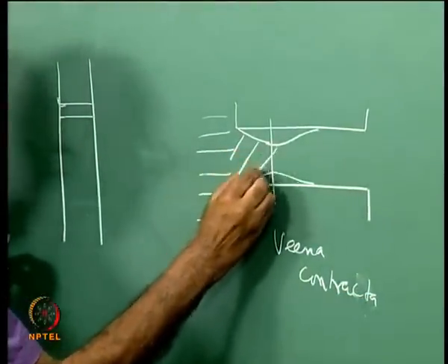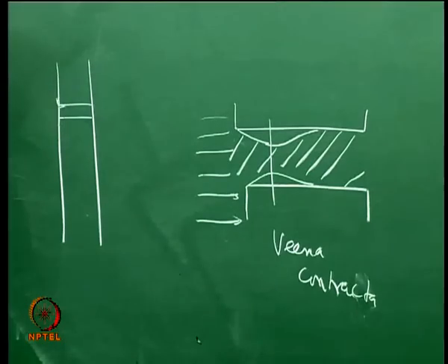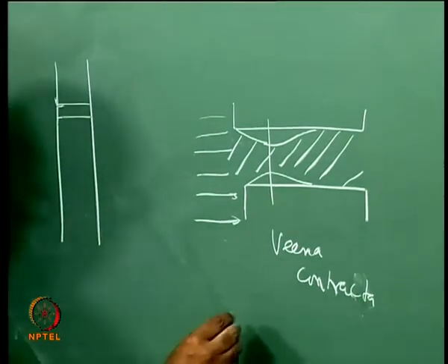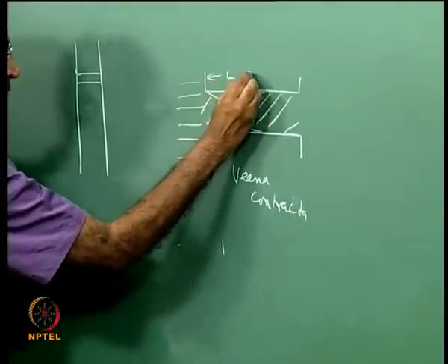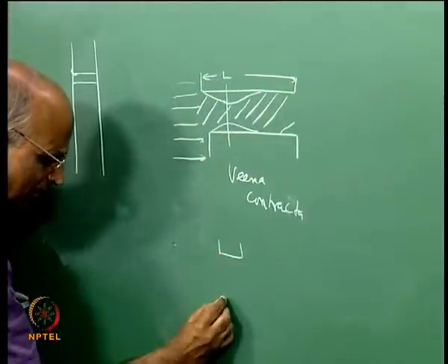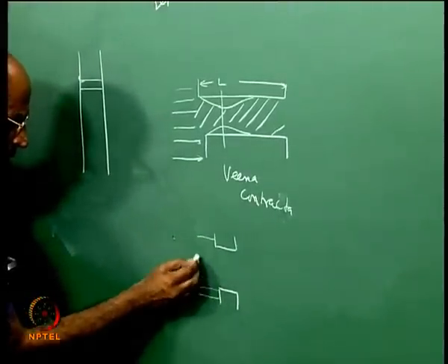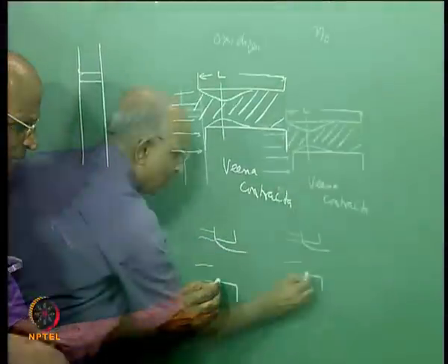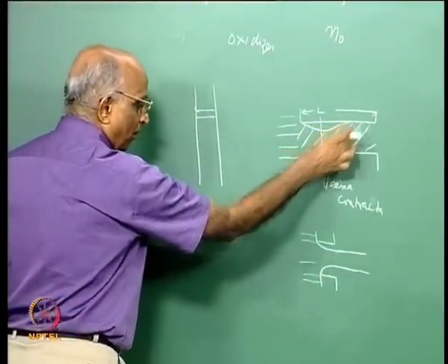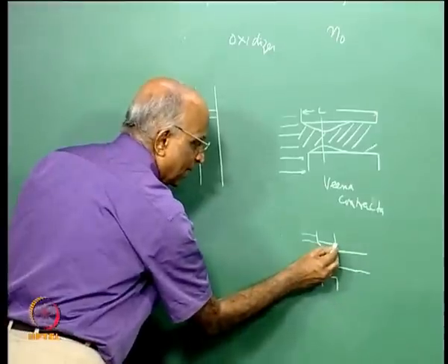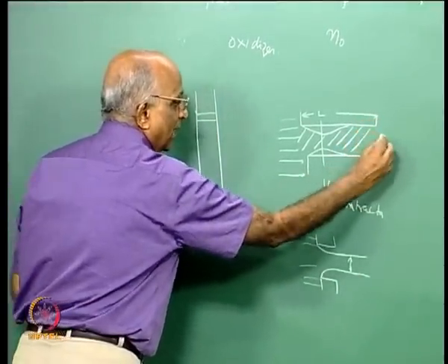In other words, this is where the liquid is flowing. If I have my shower head, which has a very small dimension, that means instead of having such a length of the orifice, my length is something like this and it is again sharp edged. The flow is coming over here and the flow now contracts and goes like this, straight. That means the flow does not reattach back to the wall, and therefore the area of flow is going to be much lower than the area of the orifice.